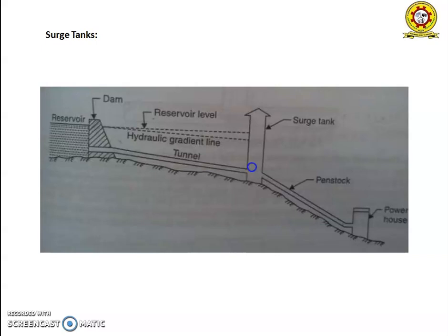It has an additional internal riser pipe provided with annular ports connected to the chamber. Those annular ports open into the outer surge shaft. When the load demand is higher, the water level in the internal riser rises quickly, thus creating a large accelerating head on the conduit in a short time. The water rises slowly in the outer surge tank, which is a larger tank, and the water flows through the ports in the pipe as it rises, and vice versa.